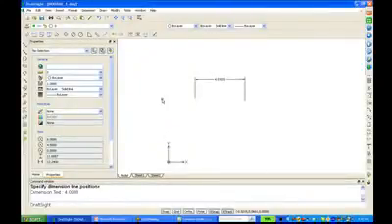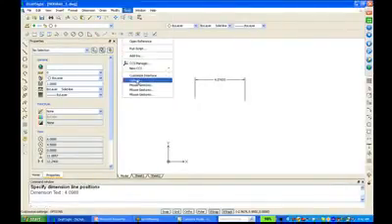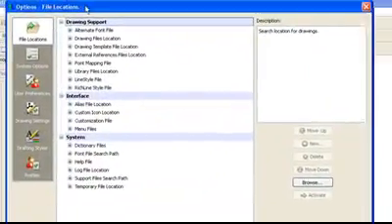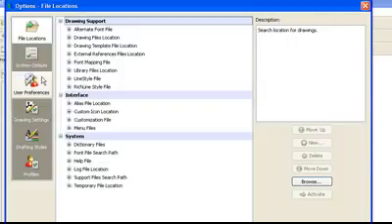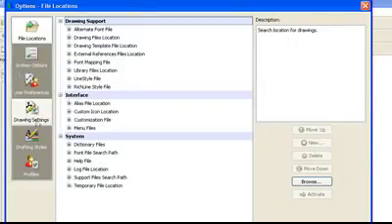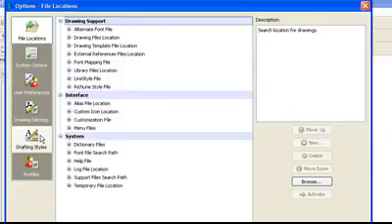There's two types of settings. I call them the system settings and the drawing settings. The system settings are the ones where, whenever you open a session of DraftSight, those settings remain. As an example, my cursor. Right now my cursor is just this pointer with a little pick box on it. I can change that by going to my options menu. In the options menu, these first two options, the system options and user preferences, are ones that will stay with the system itself. Drawing settings and drafting styles will save with the file. So we'll be creating those in a template file.